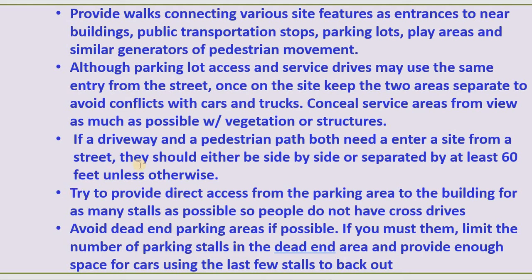Try to provide direct access from the parking area to the building for many stores if possible, so people do not cross the drive. We have the store in there so they can see it and they do not need to cross the drive. Avoid dead end parking areas if possible. A dead end means stop, no access.